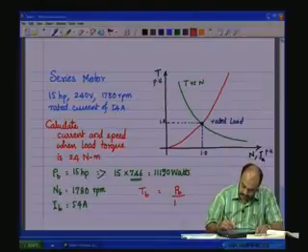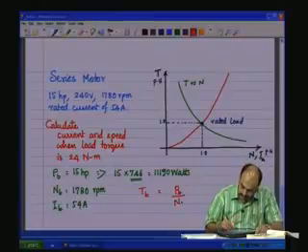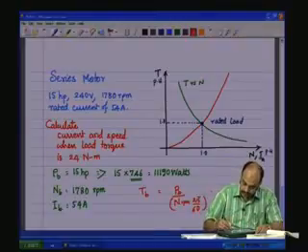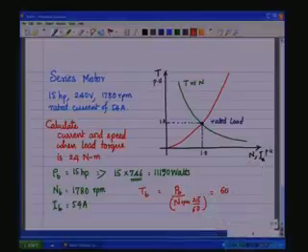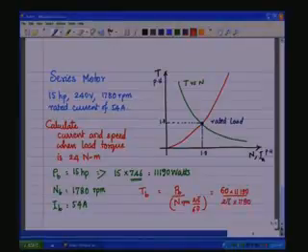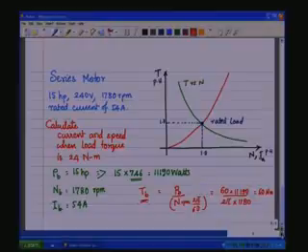But we have the speed in RPM, so n RPM into 2 pi by 60 would give radians. So, it will be 60 into 11,190 watts divided by 2 pi into 1780 RPM, which is 60 Newton meter. This is the base torque, TB.